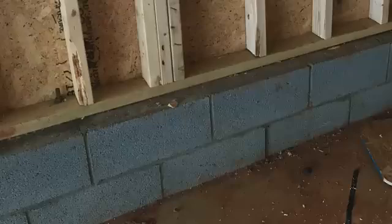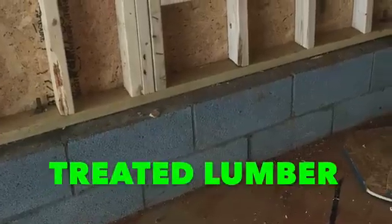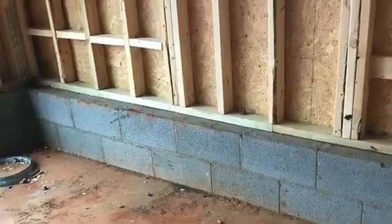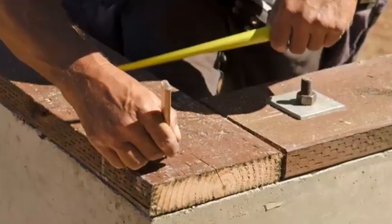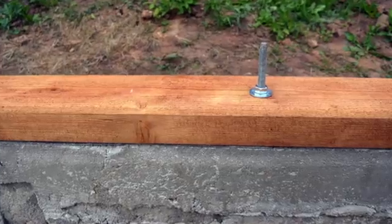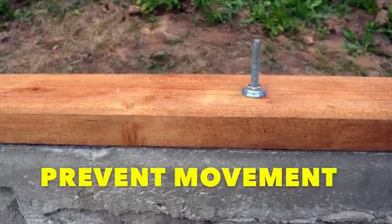If untreated wood sits on masonry, it can rot because masonry always has a moisture content. So the mud sill is made of treated lumber that isn't prone to rot. So it acts as a buffer between damp masonry and all the dry framing above it. The mud sill runs the entire perimeter of the foundation and is almost always tied down with anchor bolts, which prevent the house from lifting up when strong winds blow.